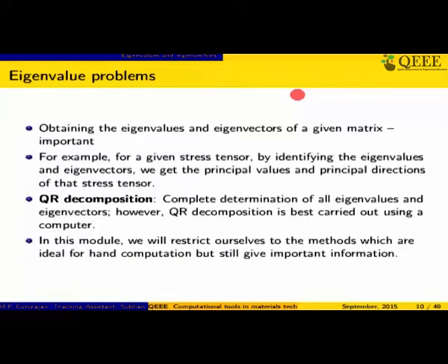So you have the so-called Mohr circle construction, for example, to identify the principal directions and principal values. What is the importance of principal values and principal directions? They are very special, because they lead to a simple scaling, and the different eigen directions are independent of each other.